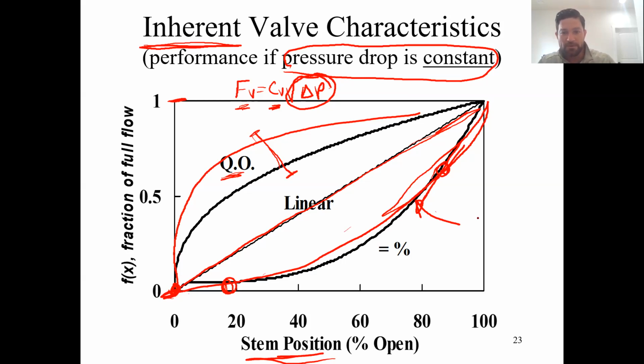So these types of equal percentage valves are used for 90% of chemical processes because of this factor. The equal percentage valves were designed to give us a relatively constant change in flow with percent opening. And we'll see how that works coming up in the next few slides.